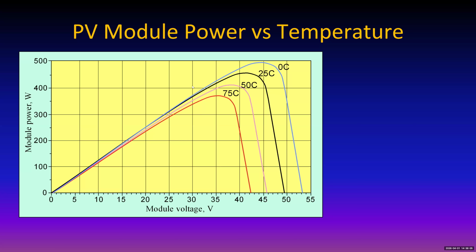And you need to design your system to make sure that it does not increase to too high of a voltage when it's cold and there's no current being drawn from the system, that open circuit voltage. And that's the sort of thing that generally happens first thing in the morning on a very cold winter day.